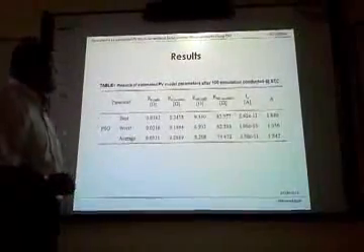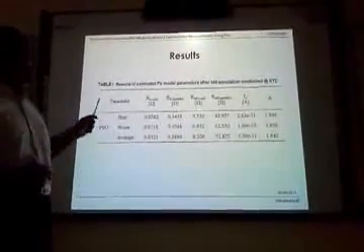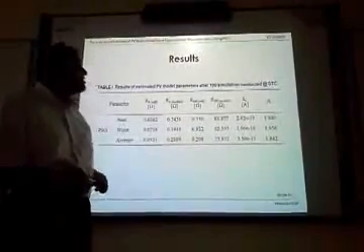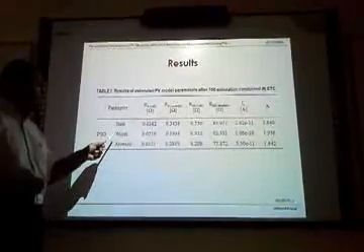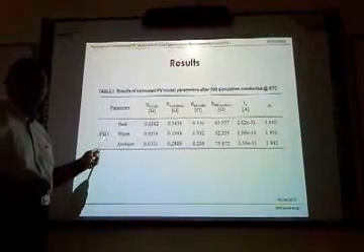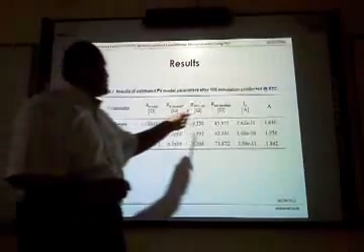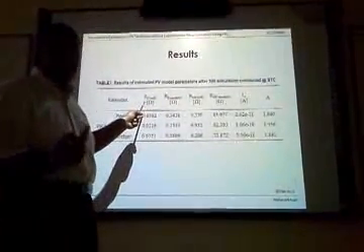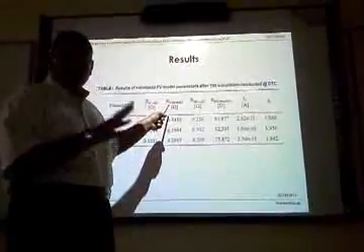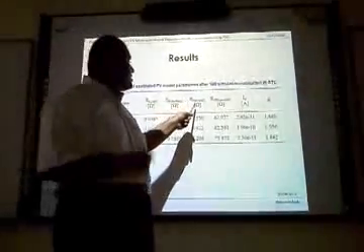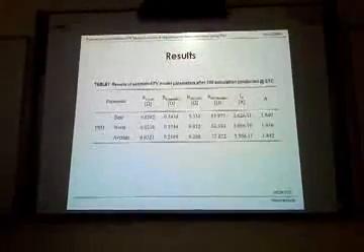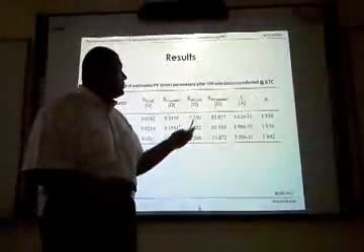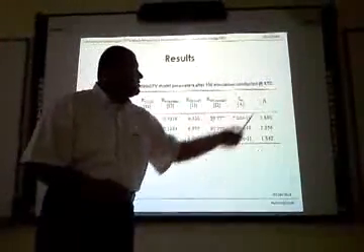Regarding the results, we run the simulation 100 times at standard test condition, and we have obtained best PSO values, worst PSO values, and the average value of these parameters: series resistance for the individual cell, series resistance for the overall module, shunt resistance for the individual cell, and shunt resistance for the overall module, I0 and the ideality factor.